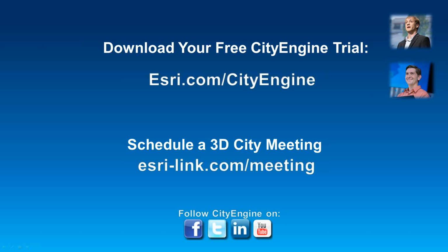Another one has to do with hardware capabilities required to operate CityEngine and model in 3D. As far as a graphics card, I recommend the NVIDIA OpenGL supported graphics cards if you're using a desktop, as well as a laptop. Those really help. So basically a heavy CAD type card would suffice, and a lot of the computers you're using for GIS typically have these. I also really recommend the 64-bit processor because huge cities take a lot of power.